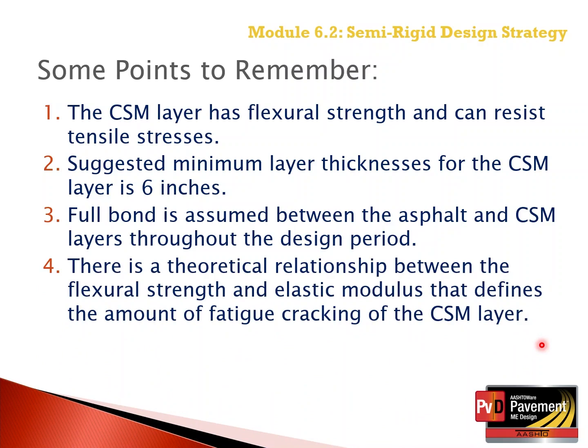And then there is a theoretical relationship between flexural strength and elastic modulus of the chemically stabilized mixture that defines the amount of cracking of the stabilized layer. And there is a unique relationship between strength and elastic modulus, all other variables remaining the same, at which the end of the design period you will end up with the same amount of fatigue cracking in the chemically stabilized layer.